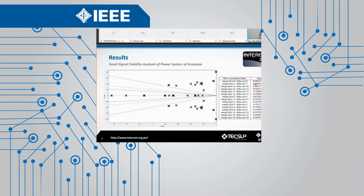But what does it mean? According to the Lyapunov method, if all your eigenvalues have a negative real part, it means that Arequipa's power system, or your power system, has the ability to maintain synchronism even though small disturbances appear.